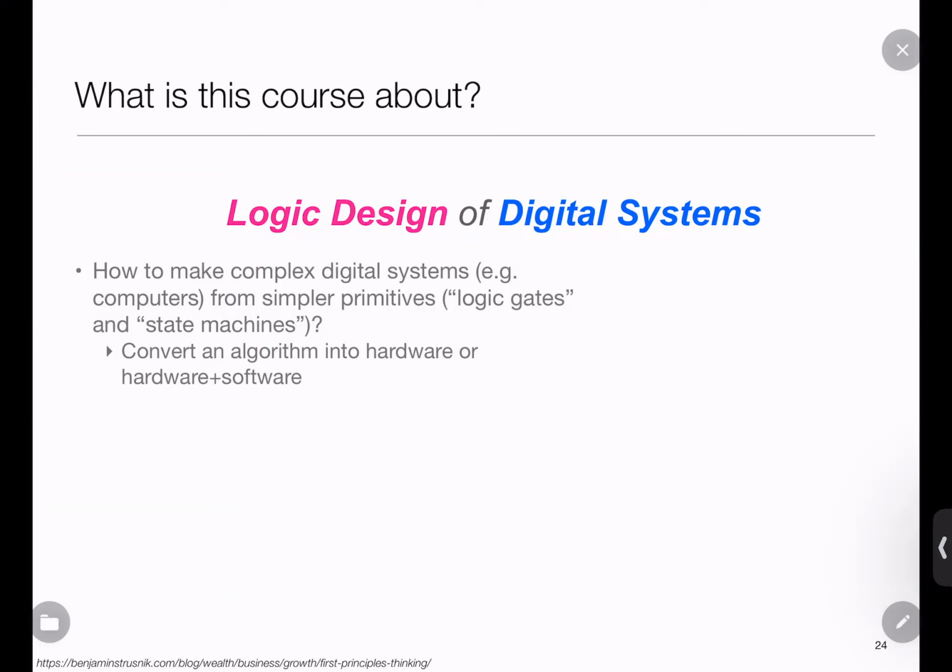State machines are basically abstractions of something happening in steps, a computation which is running in steps. You can think of computation broadly as having two elements. One is how we step through a sequence and take branches, deciding to do this or that based upon some information. The other is the actual function, like addition and ANDing. When you write code, that's what goes on. So digital systems essentially have these two things: logic gates and state machines.